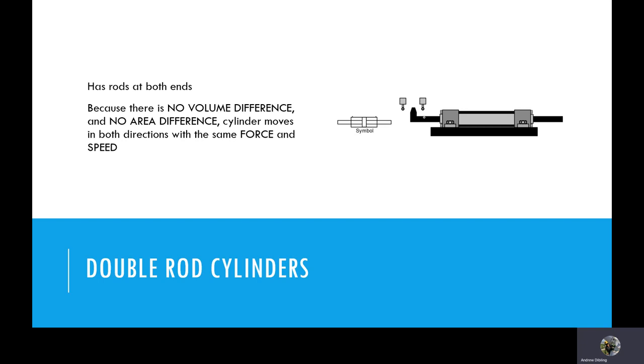They're generally not extremely high pressure devices because of the limitations and the fact that you will need to have some controls over how far they will extend. Otherwise, you can pop them through the casing. So it's important that the pressure, or the force, on these types of cylinders is limited, and that you do have some kind of a limit system. As you can see on the diagram here, it looks like they have 2 little limit switches, and those limit switches are preventing it from over traveling.